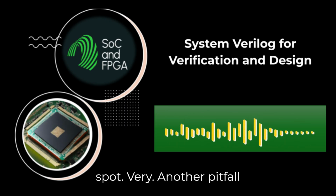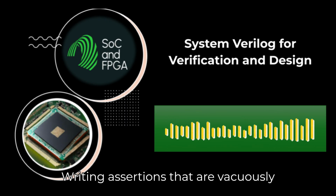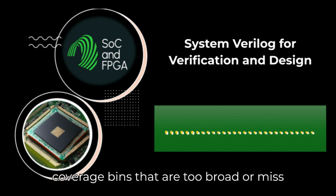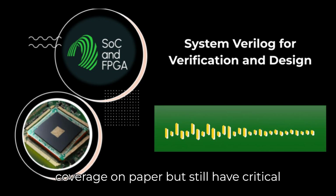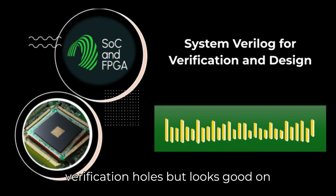Very. Another pitfall is ineffective assertions or coverage. Writing assertions that are vacuously true, they always pass because the precondition never happens. Or defining coverage bins that are too broad or miss critical corner cases, giving you a false sense of security. You might have 100% coverage on paper, but still have critical verification holes. Looks good on paper, but a trap.